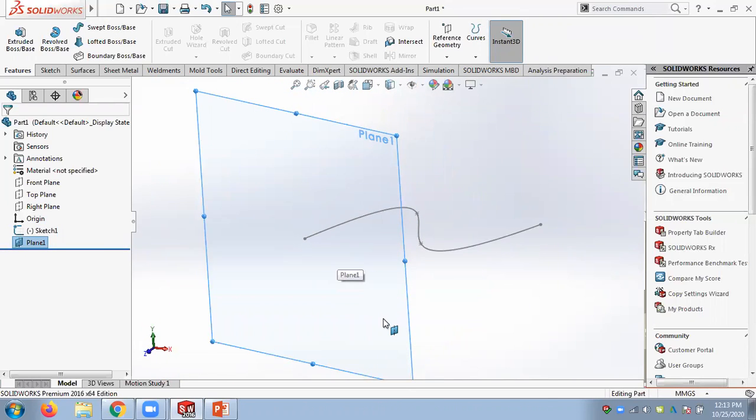So you can do it and see. Just draw. This can be an arc also. So I used the spline and exited from that one. Then I created a plane perpendicular to this point. Any questions? Let me know. Just try it and see.